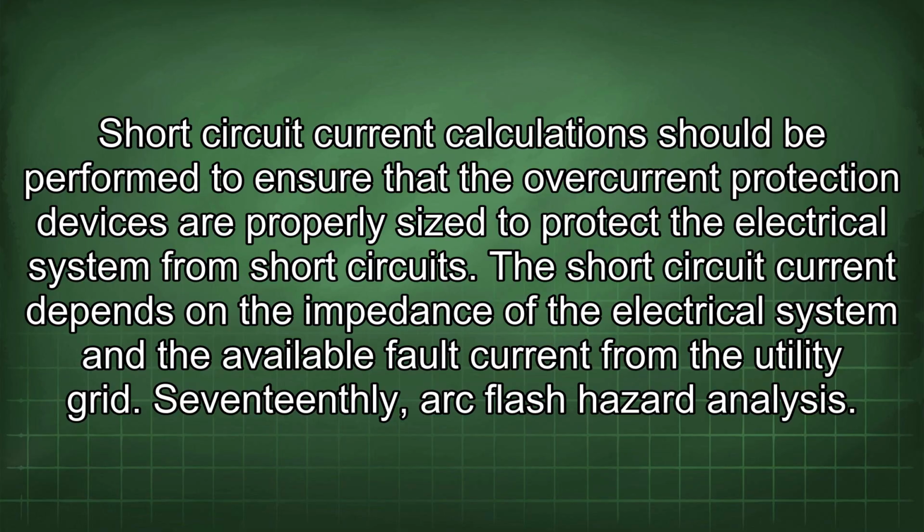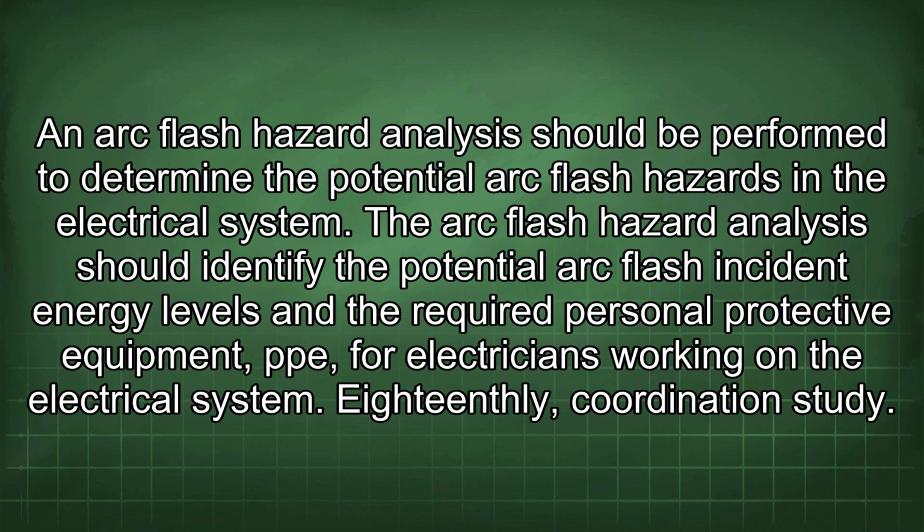The short circuit current depends on the impedance of the electrical system and the available fault current from the utility grid. 17thly, arc flash hazard analysis. An arc flash hazard analysis should be performed to determine the potential arc flash hazards in the electrical system. The arc flash hazard analysis should identify the potential arc flash incident energy levels and the required personal protective equipment (PPE) for electricians working on the electrical system.